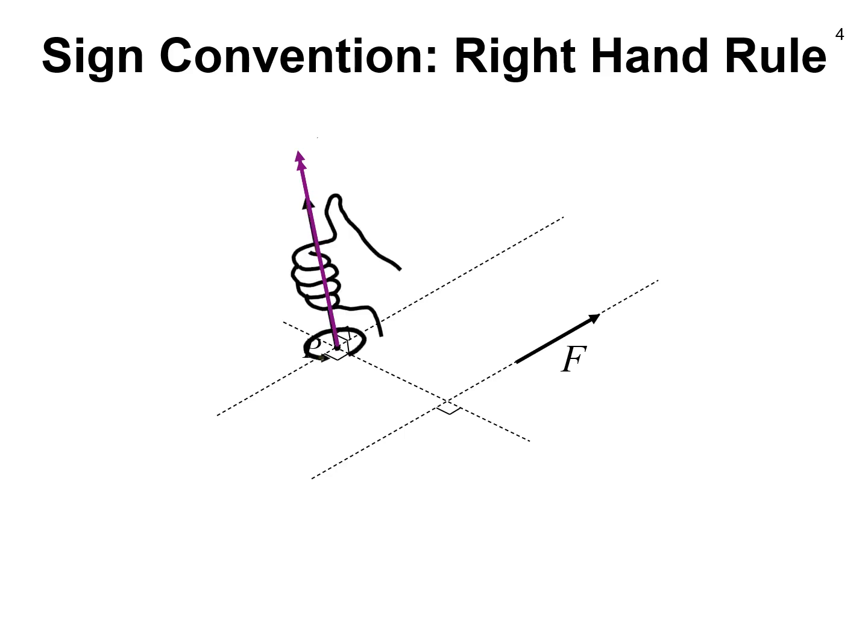That means if I take my right hand and wrap my fingers around that perpendicular vector, my right-hand thumb points in that direction, and the rotational direction that my fingers wrap indicates the sense or the positive direction of the moment. And as before, the calculation is now force times perpendicular distance, and now I'll call this the moment because now I'm calling this the moment relative to that convention.